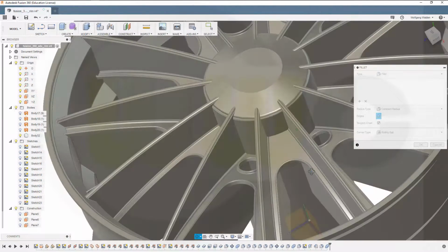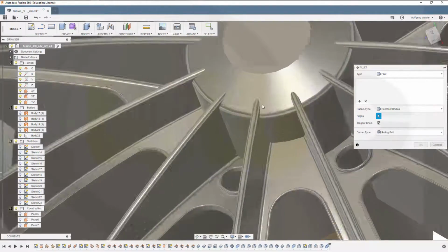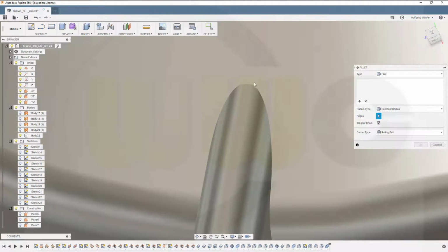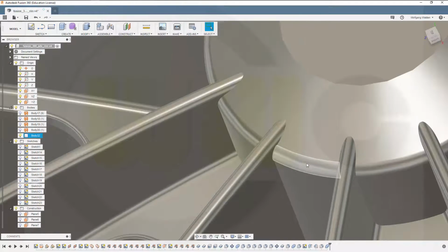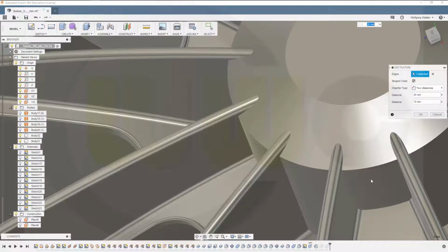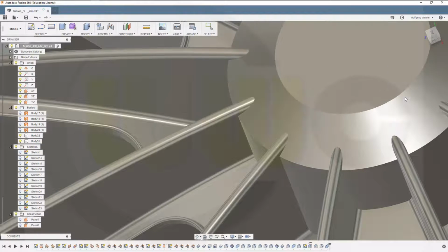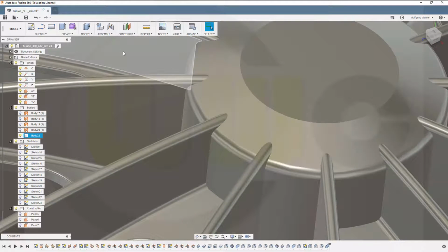So it will not go completely around. Why? Let's take a look. So maybe that's, oh yeah, there's a problem. So let's change the chamfer once more and make this, if I make this 25, now I should be able to go all around with my new fillet.